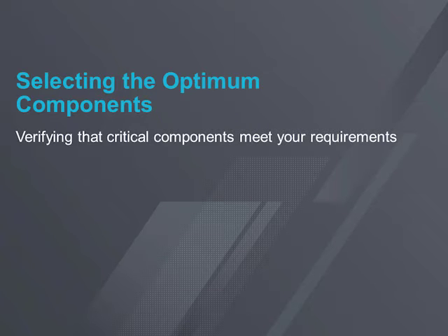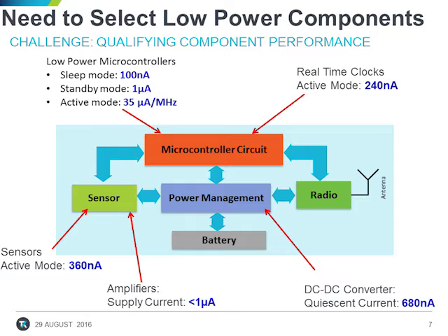To achieve or exceed your power budget, you need to optimize your design, and that means you need low power components. Fortunately, very low power components are available. Here are some example operating currents from components that have been introduced in recent years. For example, low-power op-amps on the market now operate with 1 microamp current draw. Even the microprocessor manufacturers are targeting this market with low-power products.